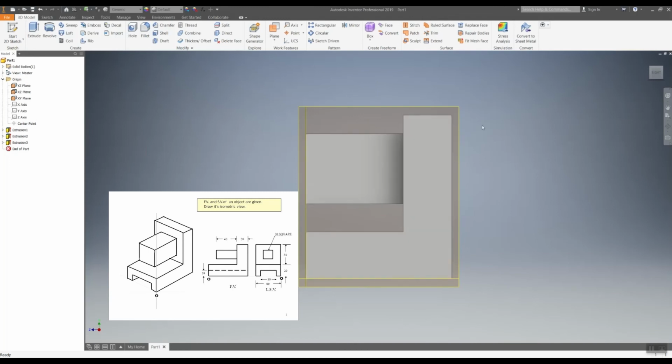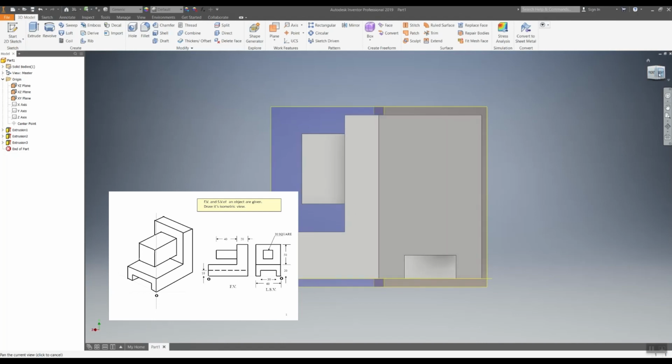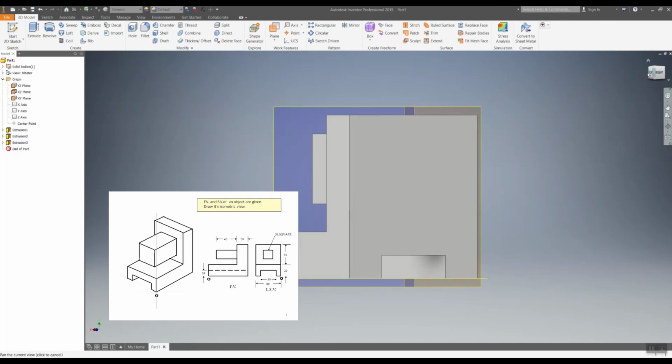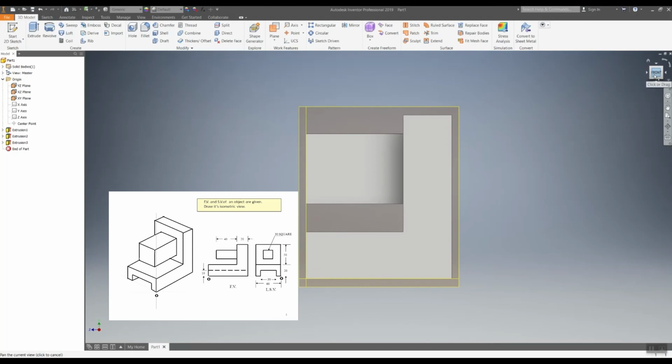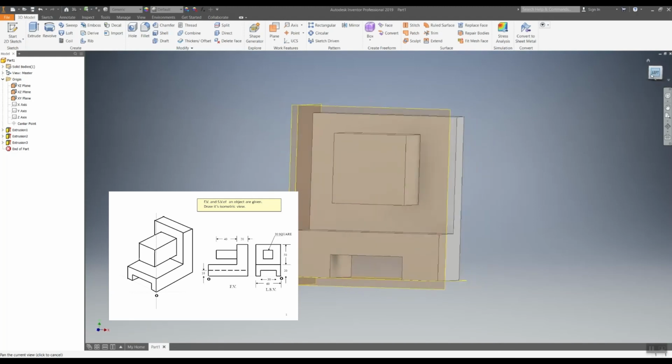Now, we've talked about this before. This is supposed to be the front view right here. We can really change that easy. If I just right click on this box, I can set current view as front. Now the right side view, front view here, and then if we go to the left side, it looks like the view on the box.